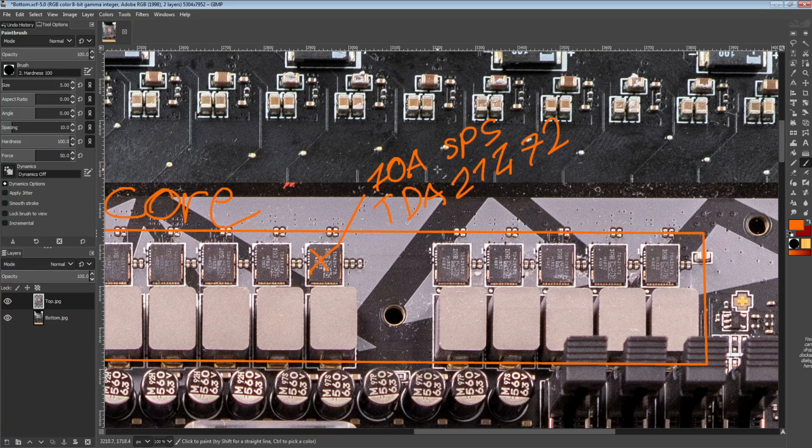These hit peak efficiency at 20 amps output, which is just a little bit under 94%, while pushing 1.2 volts. At higher voltages, the efficiency gets slightly better because you have less current. The increase in heat dissipation due to more current through the high side is less significant than the increase in output voltage.